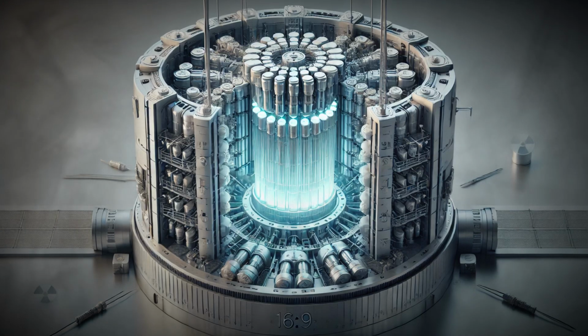The reactor vessel, a thick steel structure surrounding the core, provides additional strength and containment. It holds the fuel assemblies, control rods, and coolant under high pressure and temperature conditions. The vessel is designed to withstand intense heat, radiation, and mechanical stress over decades of operation. Instrumentation and sensors are also embedded in the core and vessel to monitor temperature, neutron flux, pressure, and other critical parameters, allowing operators to maintain safe and steady operation.